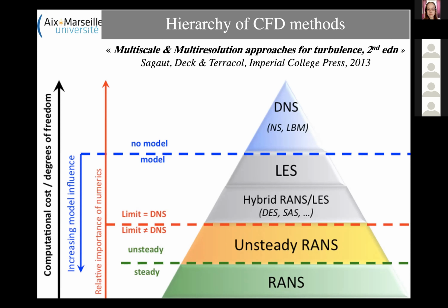And of course, here there is no black magic, meaning that solving the Lattice-Boltzmann equation, the turbulent closure problem is the same as for the Navier-Stokes equation. And this is why you use almost the same turbulence models as for the Navier-Stokes equations. And you can also have the same hierarchy of discretization of turbulent flows.